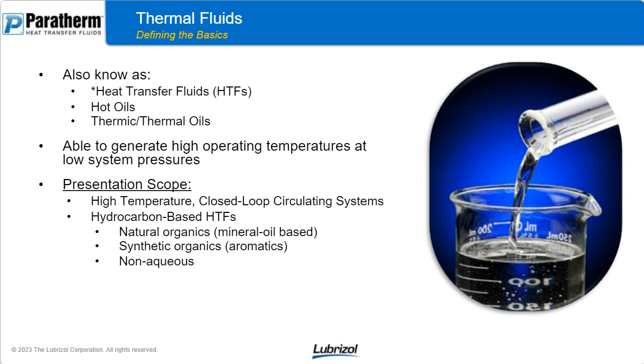Regardless of what you're calling them, though, the reason why thermal fluids are useful in an operating process is that they're able to generate high operating system temperatures without really creating a lot of pressure. And that's the real big advantage, because with pressure comes complications to your operation. Increased pressure decreases the safety margin, a lot more maintenance has to go into things, a lot more complications and attention needs to be paid to the system.